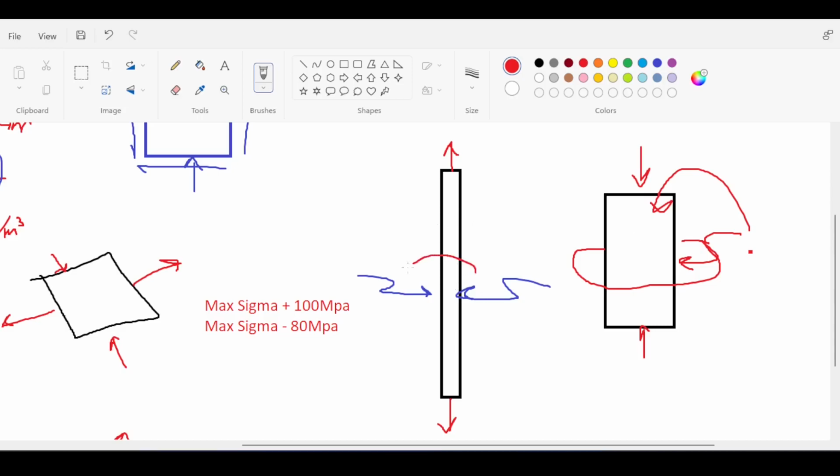Similarly, the hydrostatic pressure, or in this case, the pressure in the other direction, will have an effect on the load carrying capacity. Taking each sigma on its own is okay, but is not really accurate. You need to use both sigmas to get one equivalent stress.